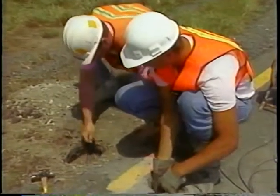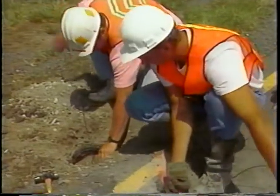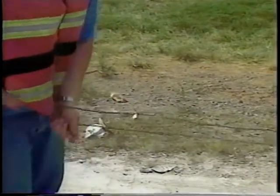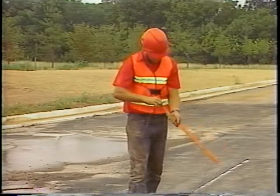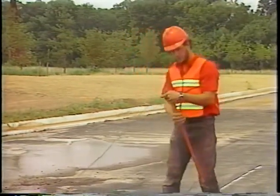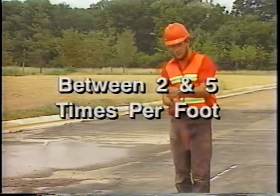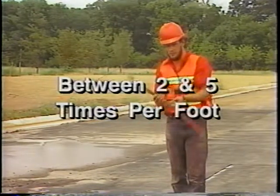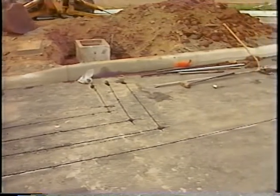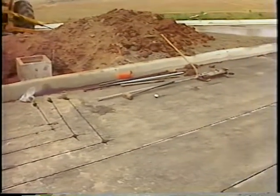After inserting the wire, you will have 2 lead-in wires from the beginning and the end of the loops. These 2 wires should be twisted together to form a pair from the loop to the pull box. Using a twister is a lot faster than doing this job by hand. To avoid crosstalk, you should twist the wire between 2 and 5 times per foot. And if you are installing adjacent loops, make sure you twist all the lead-in wires in the same direction.